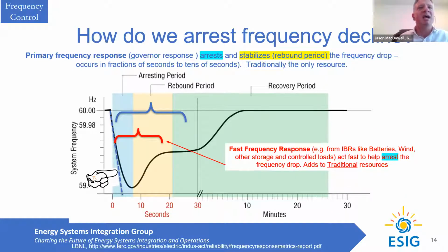The initial decline, as you have more inverter-based resources without capability to support frequency and voltage, yes, the decline might get a little bit steeper. But today, in the interconnected systems, that's not a problem. There's certainly capability from inverter-based resources, from fast frequency response, primary frequency response, to provide energy to rebalance the system and bring the frequency back and recover after an event.